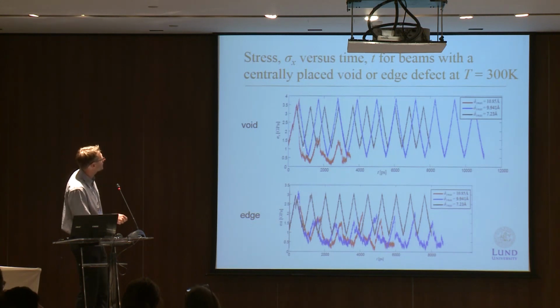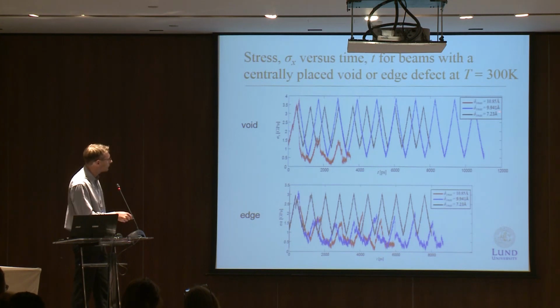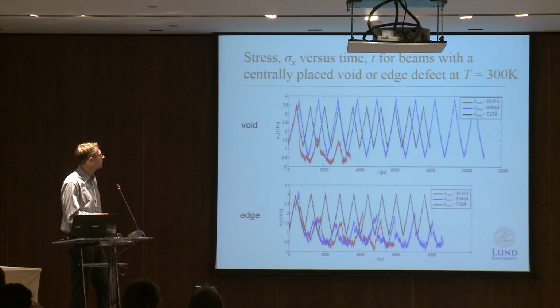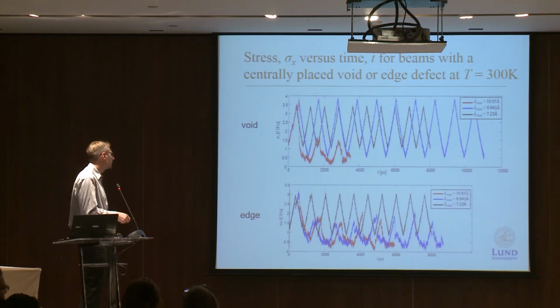In this first case, it actually breaks already after 3 load cycles. Then we decrease the load, not very much, but a small amount, and then we get a completely different behavior. We still have plasticity in the first load cycle, but then we reach a steady state and would expect infinite life in this case. And the same is true for the lowest value. Then we reach steady state immediately, and it looks the same in all load cycles.